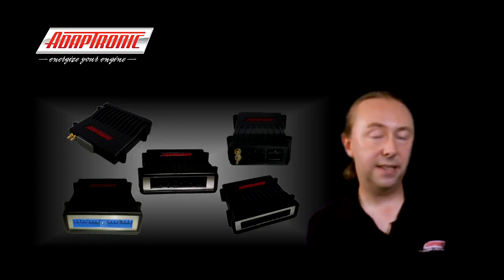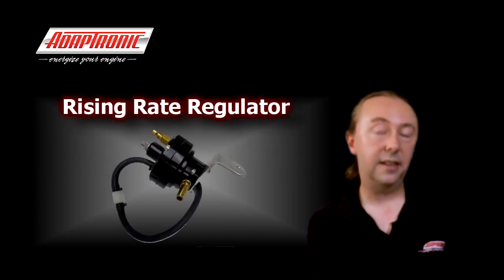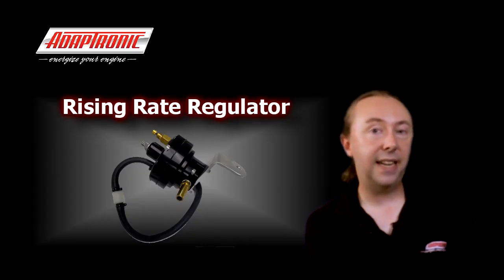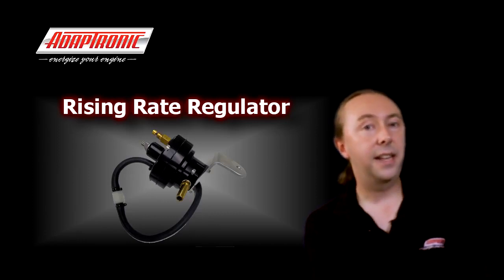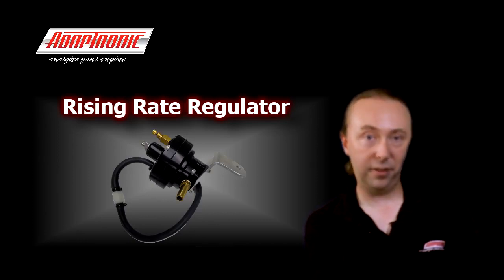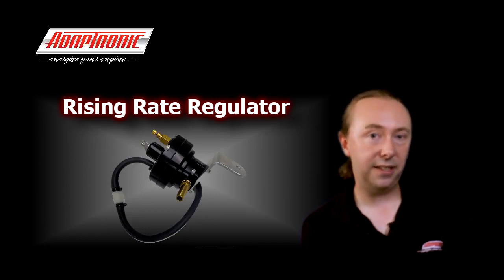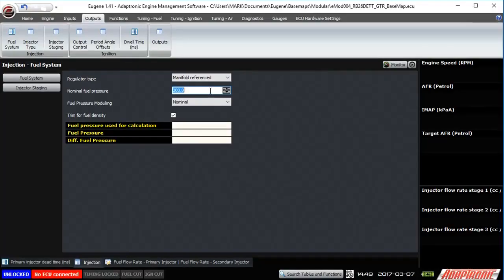The type that the ECU doesn't support is a rising rate regulator. So in a rising rate regulator, the fuel pressure actually changes at a higher rate than the manifold pressure. So you might see, say, a 10 kPa increase in manifold pressure, and that might mean an increase of 20 kPa to the fuel pressure. If you have a fuel pressure sensor, then the ECU can measure that pressure and then adjust the injectors to suit. The next setting is the nominal fuel pressure.